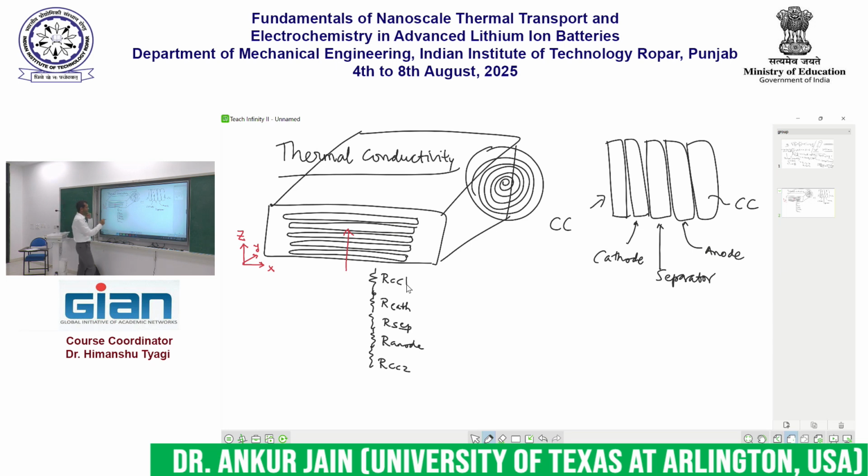In other words, Ri, where i is the ith component, is given by Ti over A Ki, where Ti is the thickness of the ith component and Ki is the thermal conductivity of the ith component.